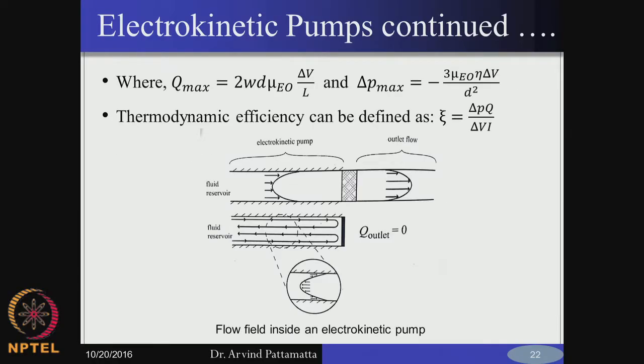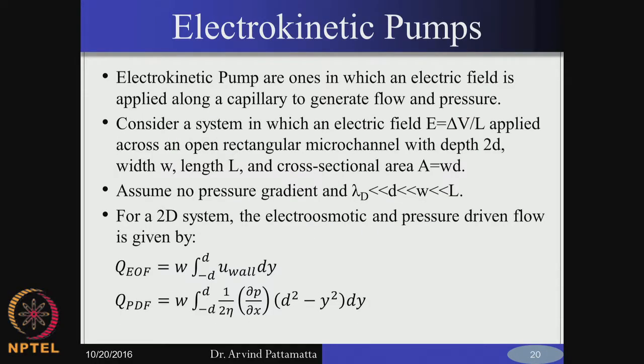So what is the application of such electroosmotic flows? One is when you design what are called electrokinetic pumps. These are not conventional mechanical pumps where you drive flow purely by pressure gradient. These are flows where you can have simultaneously both electroosmotic driven flow plus a pressure gradient driven flow.